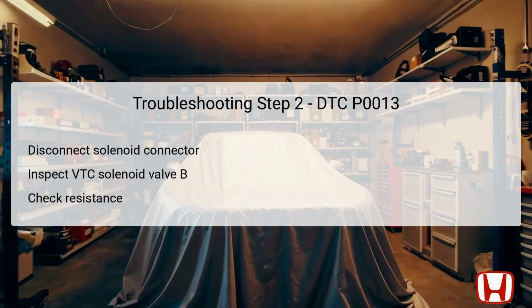If the reading falls outside this range, it indicates a defect in the solenoid itself, requiring further action for replacement or repair. Assessing these values allows for the determination of the component's operational health. In the third step, you'll disconnect the PCM connector to initiate a detailed circuit inspection.